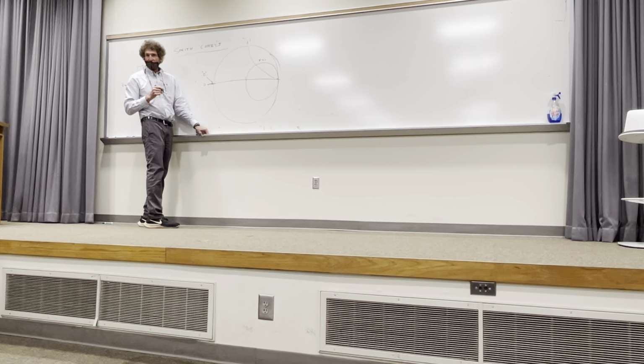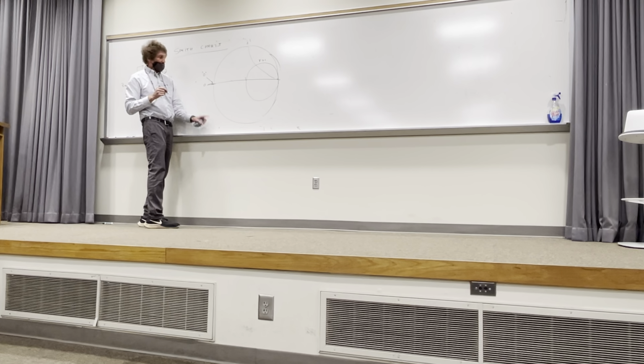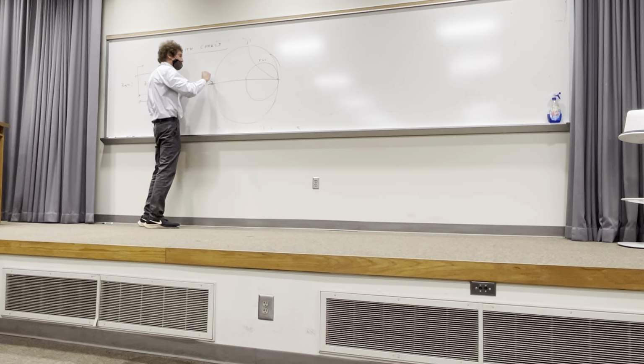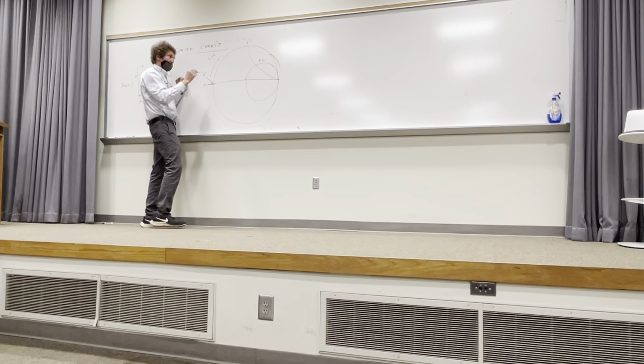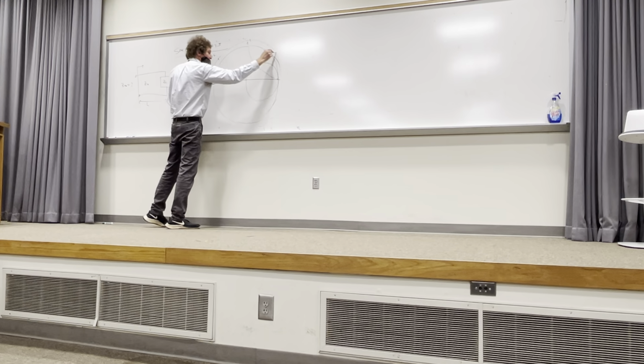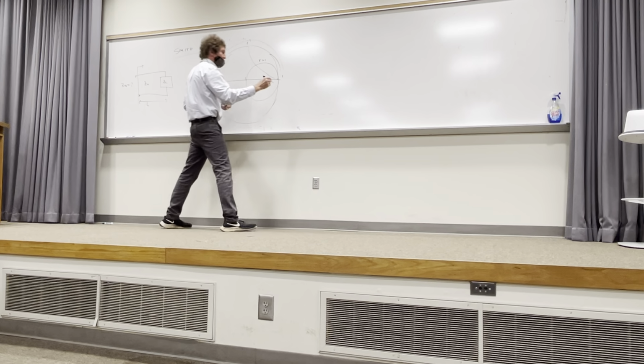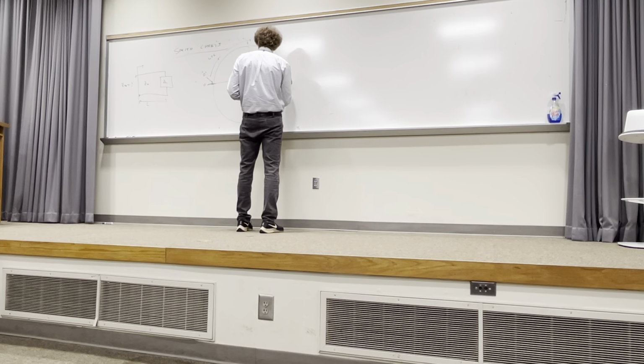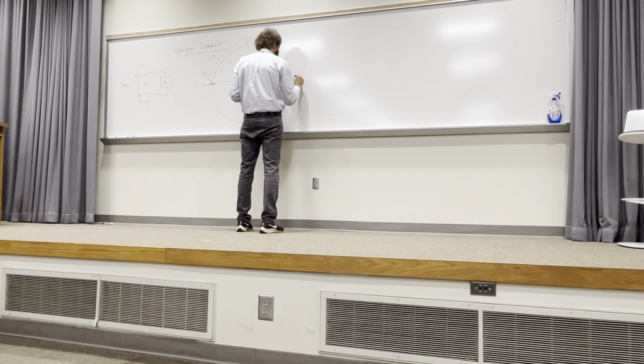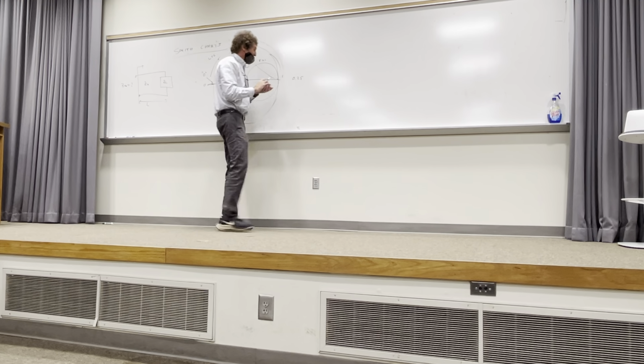If you look at your Smith charts, can everybody locate that point? You all see how it's 0, right? Now, if you go in this direction, this is wavelengths toward generator, go around. When you go exactly a quarter wavelength, you'll see it will be at 0.25 in wavelengths.